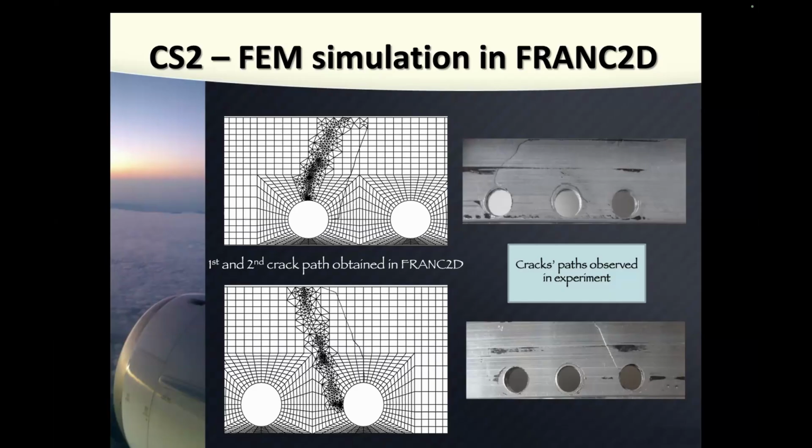And I used automatic mesh creation here. Automatic, I just wanted to see what the result of the simulation was. So check this. Crack growth here compared to this, and crack growth here compared to this. You can see they are almost identical. And you can see here in this dashed line, that's the crack from the other side, because this was done at the same time.